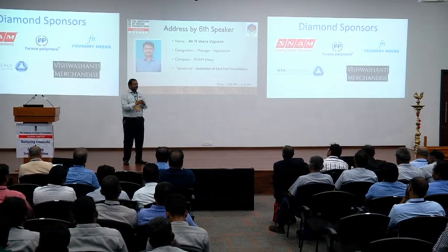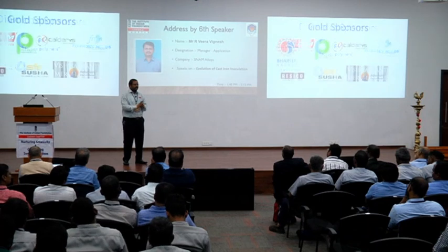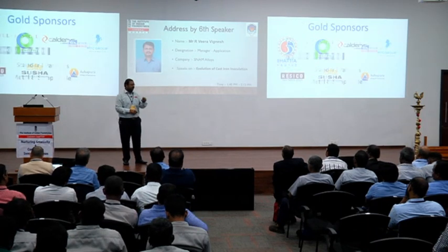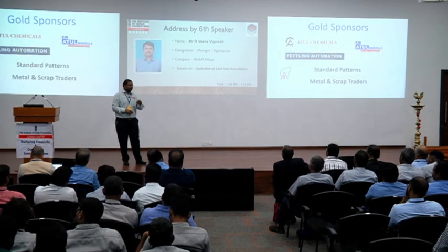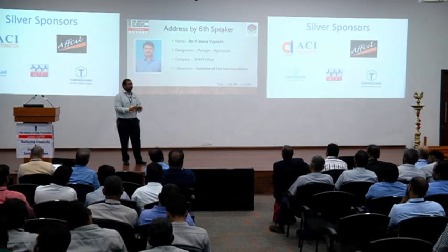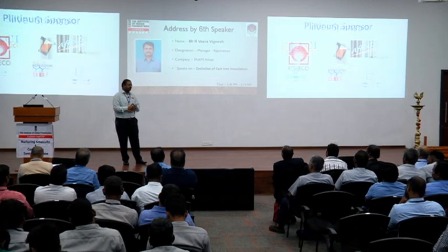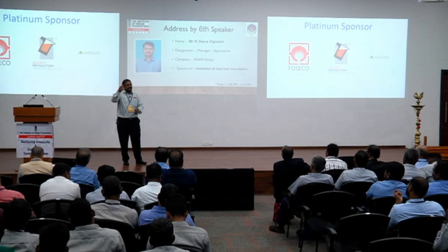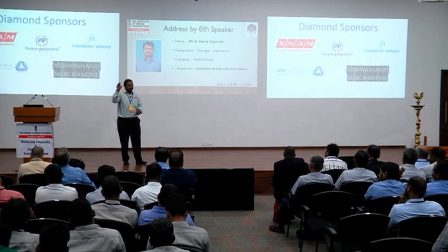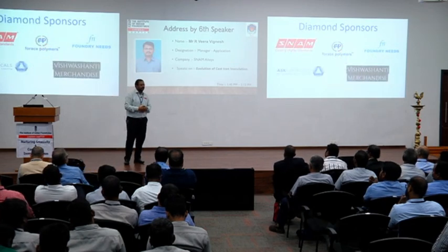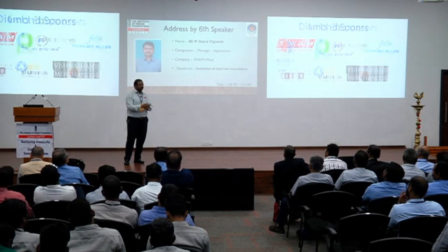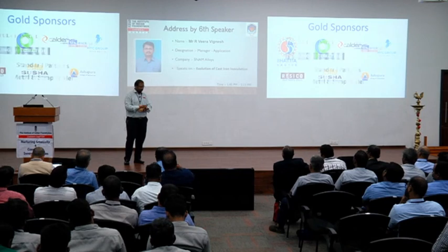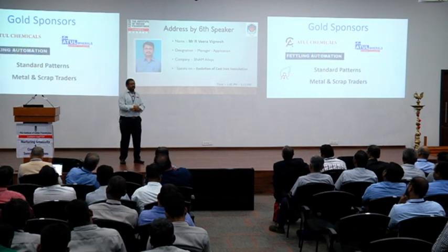Sir, these are elements similar to iron, which cannot be done anything with respect to inoculating elements. What inoculating elements can do is react with whatever is not required for your casting, say for example, oxygen, sulfur, phosphorus, nitrogen. These elements have got affinity towards these reactive, electronegative elements, like the elements which come to the right side of the periodic table. So moly, vanadium, chromium are equivalent to iron, as dense or even denser than iron.